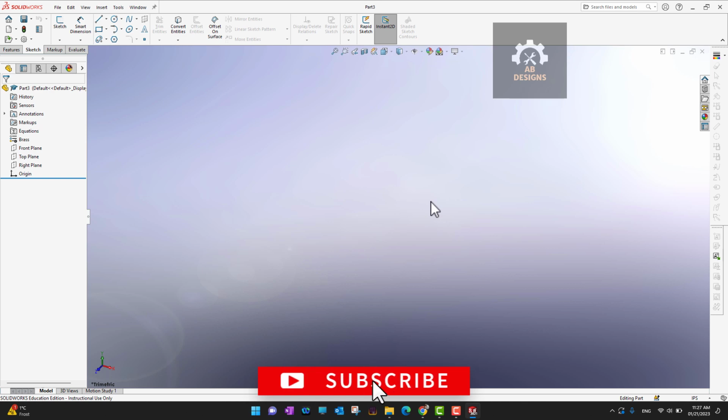If you save your template into the default folder, then automatically you would find that in your SolidWorks. And if you want to save this template for some specific company folder or somewhere, you need to add the path to the software. I would recommend that you use such templates in Dropbox or somewhere where all other people can access them, so it can save their time as well.